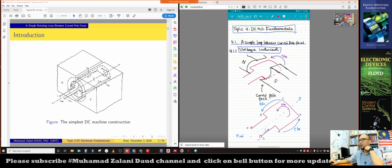For example, referring to this figure, we can say that the voltage will be induced across AB, which is EBA here. Across BC we might assume a voltage will be induced, but when we calculate, there will be no voltage across BC; ECB equals 0.